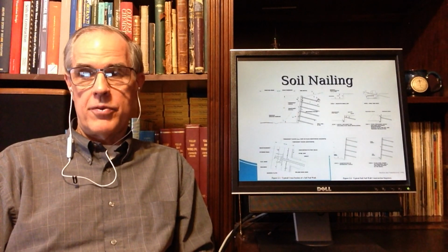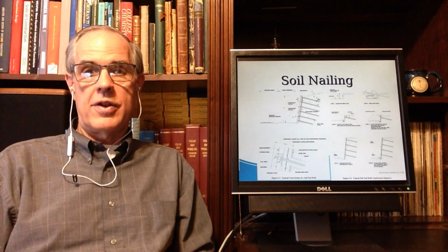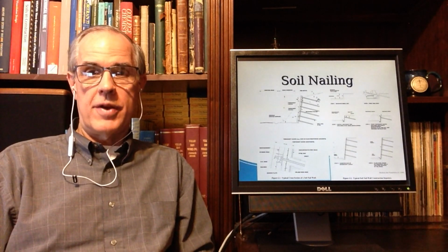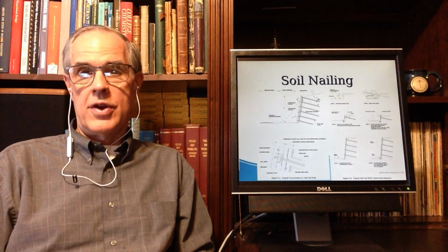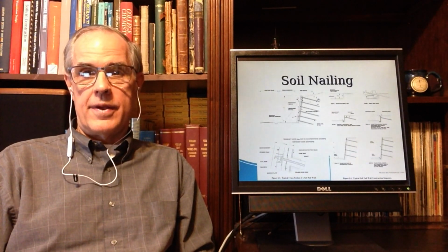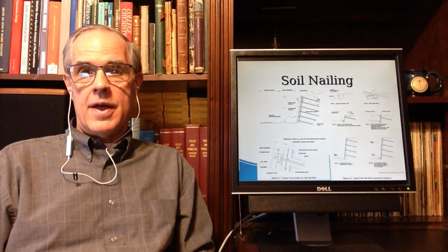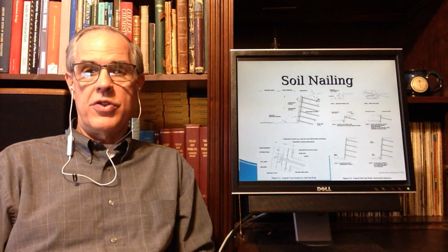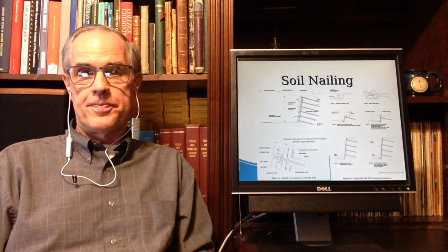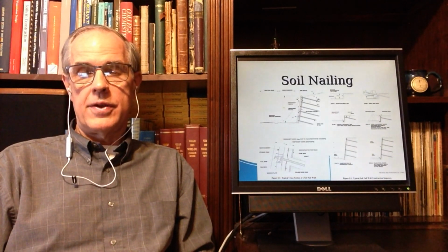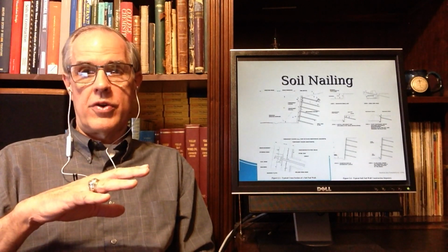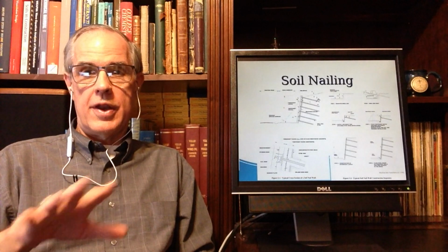With soil nail walls, I will warn you, you need to consider your drainage. That's also true with rock nailing, especially if you're in an area like ours where you have a great deal of artesian water. So that pretty much concludes this portion of the course relative to the first two types of walls we've considered, which are concrete gravity walls and MSE walls.